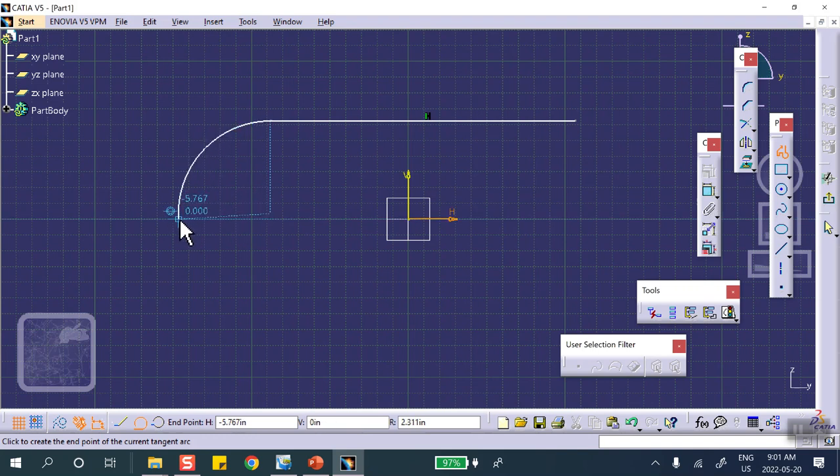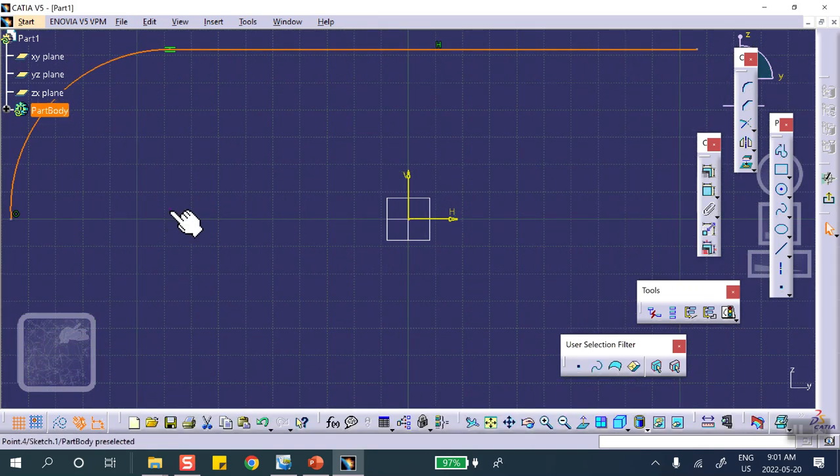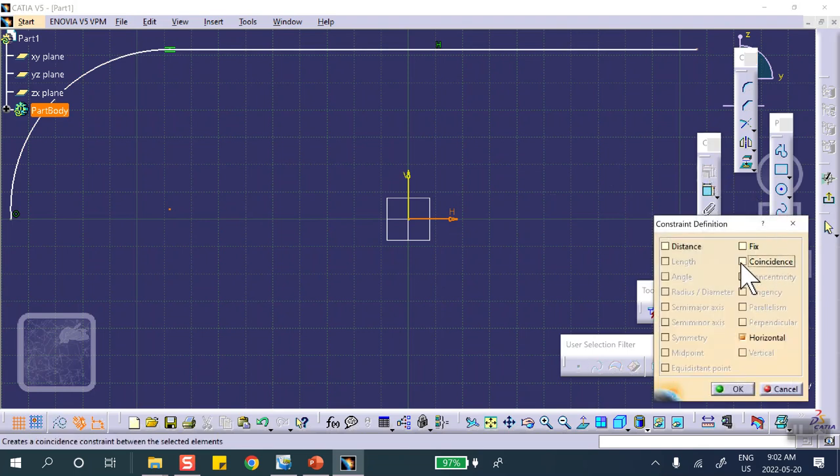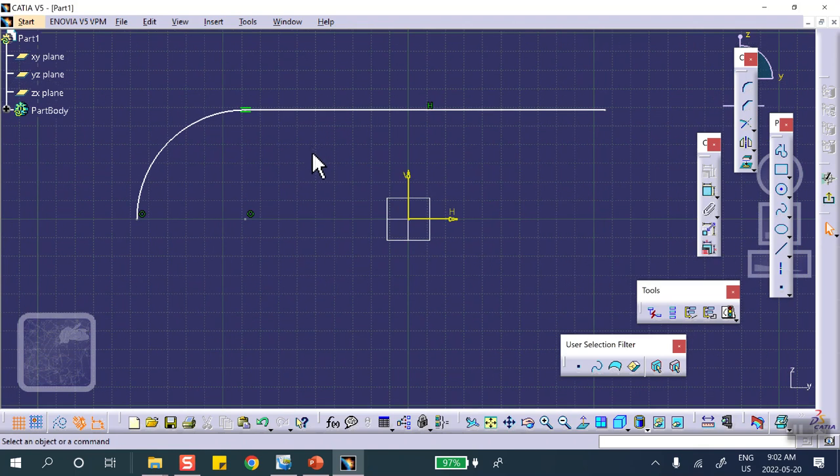So I'll do it right the first time. Okay, this is also not cleaned up. Look at where the center is. It's not on that line. So I can select this, control that, make it coincident. Okay, now it's right. Ignoring dimensions. I'm not going to bother doing the bottom piece. You can if you want. Basically, you should mesh it later on.